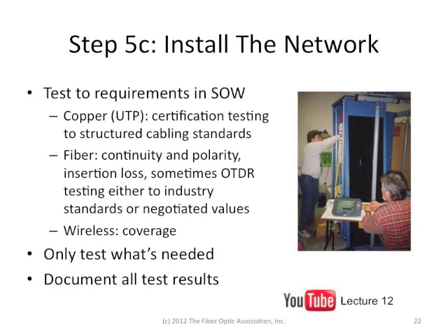One of the things to do is only do the tests that are needed. We often find people calling for OTDR testing, for example, on short premises cabling, where it makes absolutely no sense at all, but adds tremendously to the cost of installation. If it doesn't need testing, don't do it.